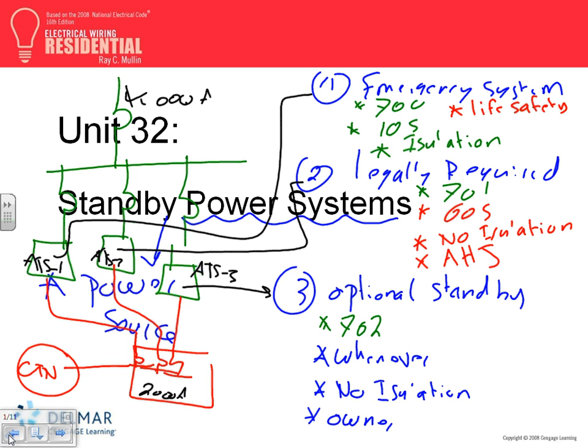So the first thing, you energize that generator. Within 10 seconds, it will energize and the auto transfer switch will pick up. Then the second auto transfer switch picks up within 60 seconds. After that, the auto transfer switches, you guys can delay them. These have delay on them. You can delay this one to start after 10 seconds. Then when everything is up, you can tell this one to start after 60 seconds, and you can delay that. So then you transfer these within 10 seconds.